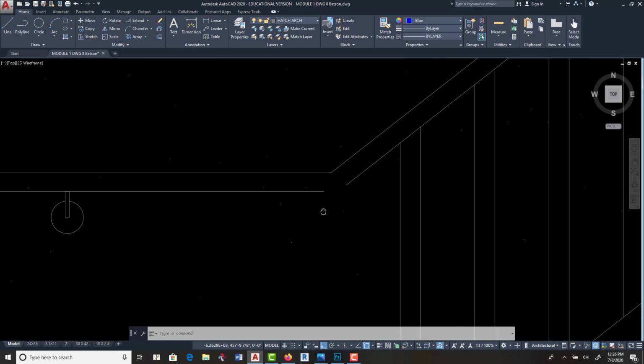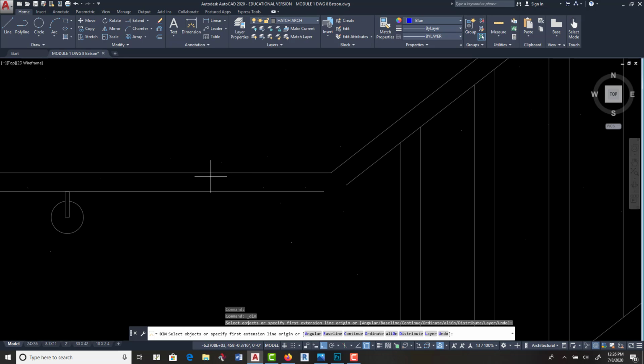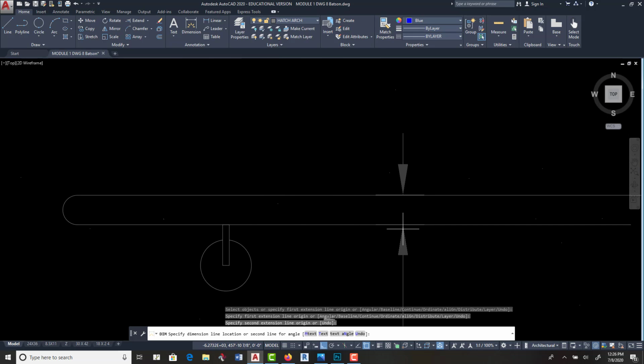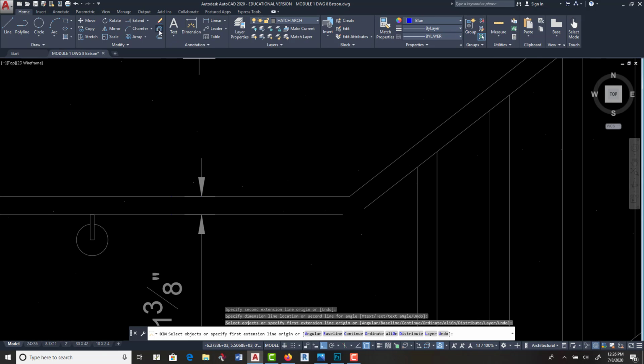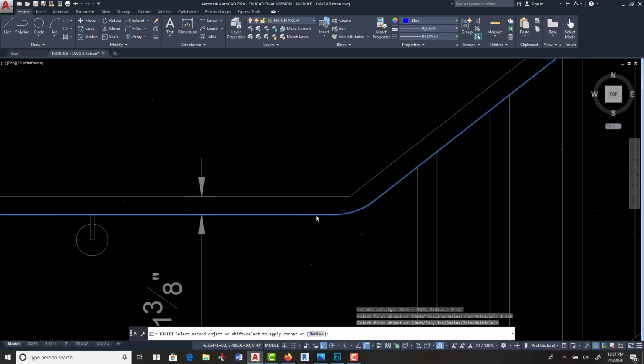The railing is, let's first find out the railing. All right, let's see. I'm going to do a dimension. What is this railing? I'm going to go to near inner and go up here. Okay, oops. I'm going to do this railing. Let's see, what is this railing? It's 1 3/8 of an inch. So I know that the fillet radius is 1-3/8, enter. So left select and left select, okay?